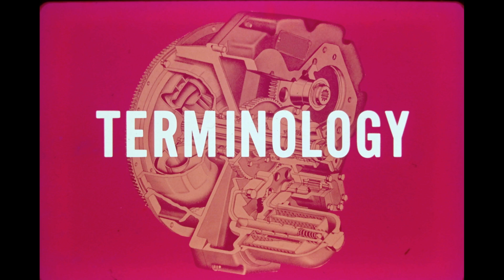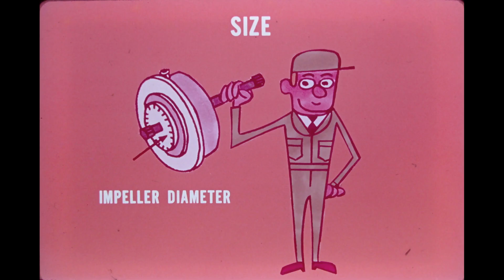Now that we've discussed the basics of torque converter operation, let's look at the terminology used in the sales and service manuals. First, the size of the torque converter is determined by the diameter of the impeller. For example, the TD25C is listed as having a 17-inch converter. This means simply that this converter has an impeller 17 inches in diameter.